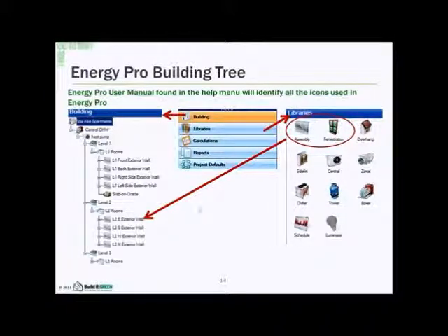So why include the common area? There are two reasons: I like to see the whole building in the energy model, and this common area has a play on what the residential building or portions of the building is experiencing. Then I feel like you should model it. But if it's separate, totally far, and has no relationship with the building, then it doesn't need to be modeled. But that's just my approach to it.